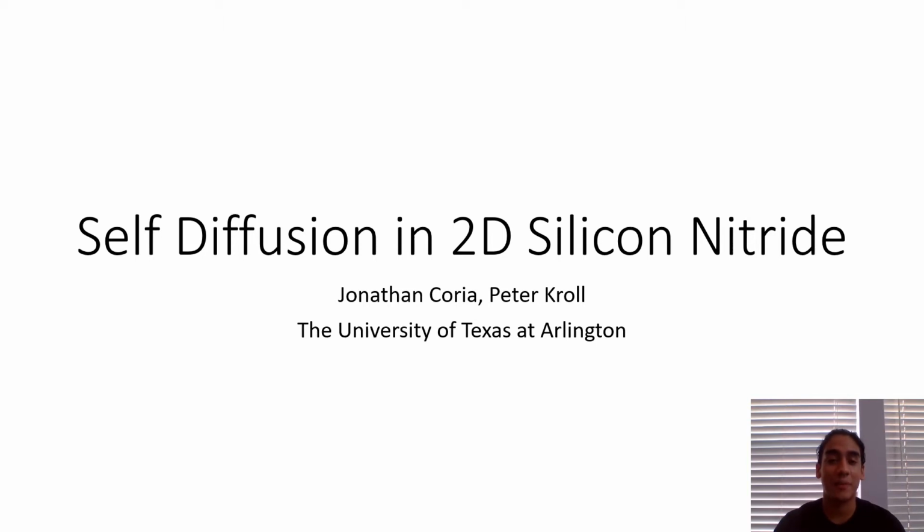The research that I'm performing focuses on the diffusion of nitrogen in amorphous silicon nitride across a range of different temperatures for certain periods of time through the use of molecular dynamic simulations. Silicon nitride ceramics are polycrystalline structures that are known for their thermal stability and shock resistance at high temperatures, so being able to understand the interactions and movement of silicon nitride can provide useful information to those who seek its potential. The goal of these molecular dynamic simulations is to acquire a mean square displacement and relate it to a diffusion coefficient that can then be used to find activation energies for specific temperature ranges.